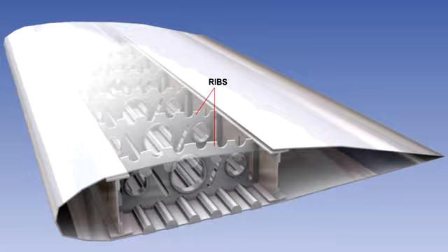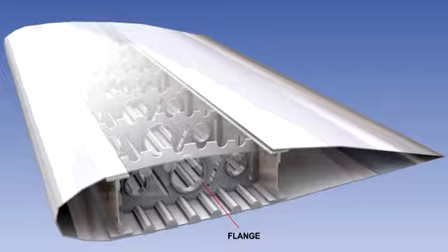Ribs maintain the aerofoil shape of the wing, support the spars, stringers, and skin against buckling, and pass concentrated loads from the engines, landing gear, and control surfaces into the skin and spars. Ribs often have lightening holes cut into them. As well as reducing the weight of the structure, these holes are usually flanged to help stiffen the rib.